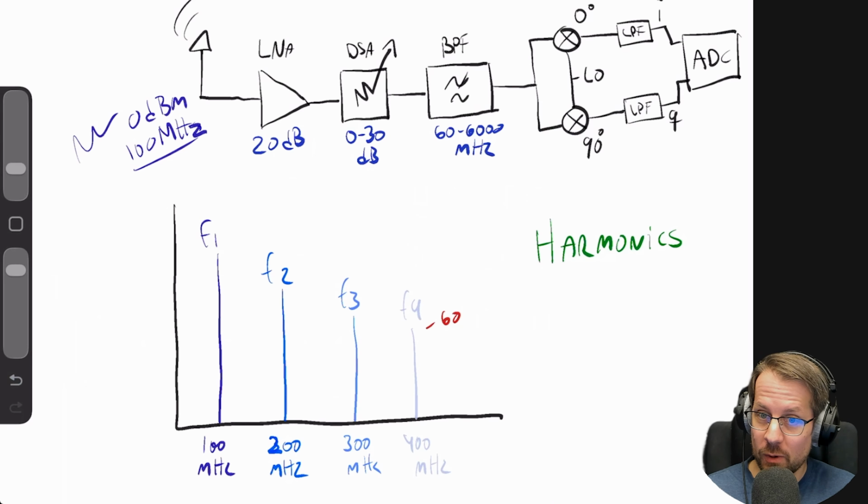If you move further away from your antenna and all the harmonics disappear, then you know it's being generated from inside your spectrum analyzer, because if it was real and it was actually being broadcasted out in the air, harmonics wouldn't completely disappear when you start to move further away from your antenna, right? So that's one easy way to do it, or add some attenuation in front.